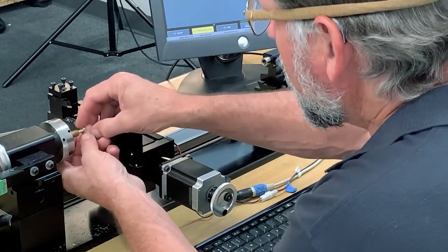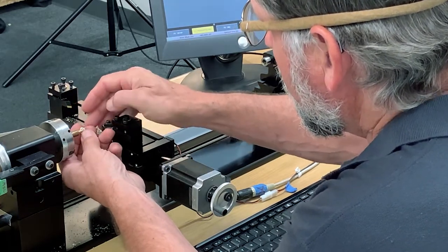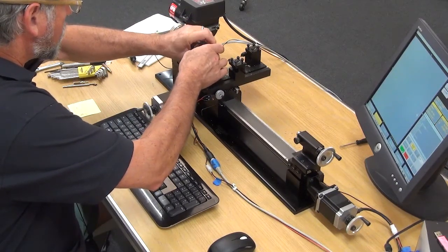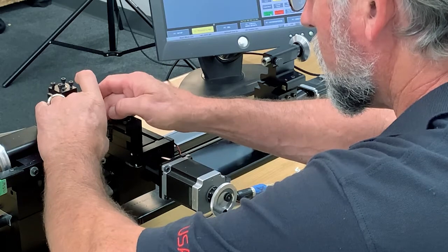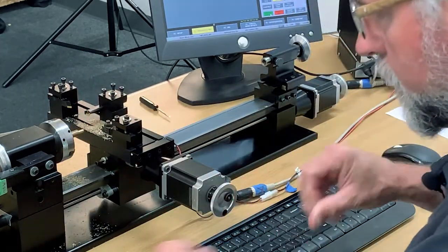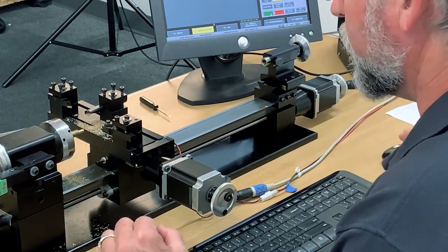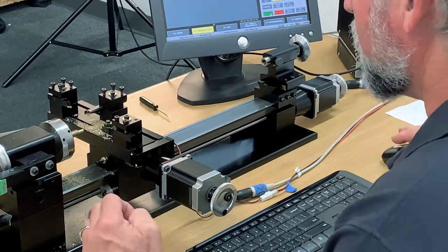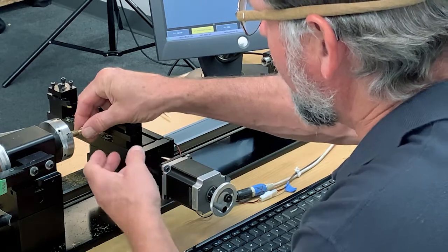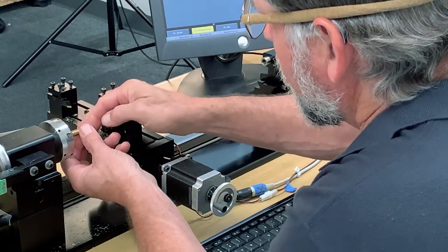There, and we'll see if this is going on. Let's go this way. Okay, starting the thread, it's still a little snug, so I'm going to run a few more passes here until I get it on size. I won't bore you with this, and then we'll come back and move on to the next one. So I've moved it in 8 thousandths now. Total of 8 thousandths, 2 thousandths for each run.